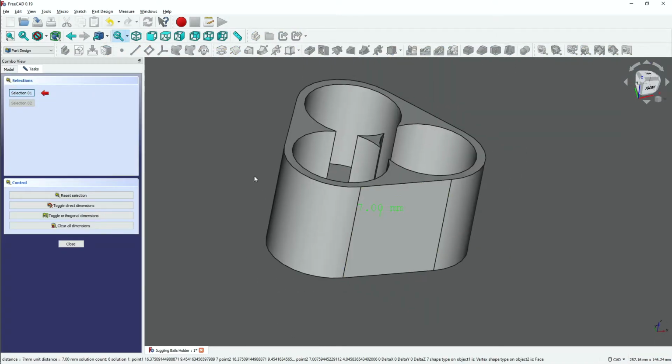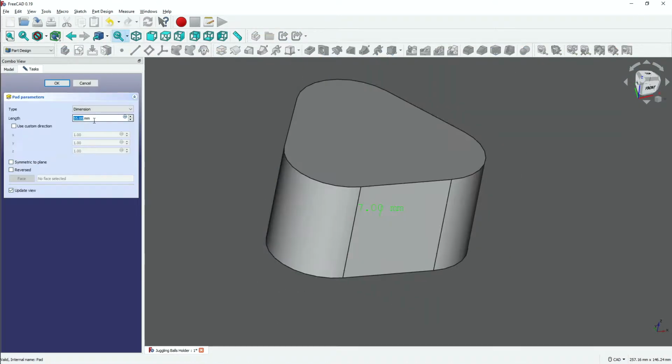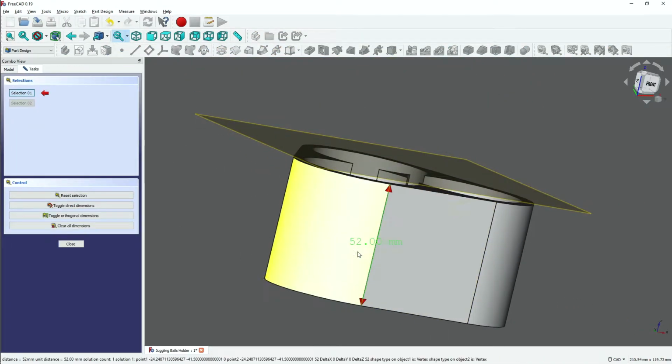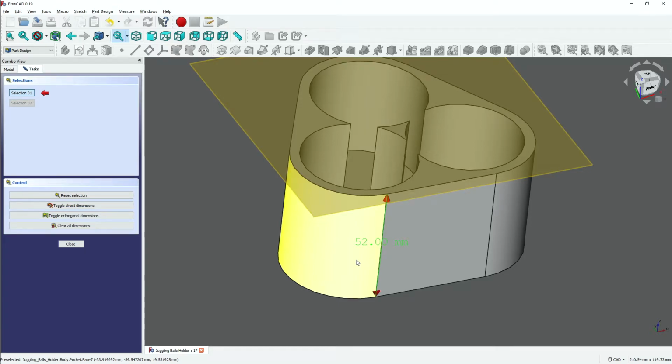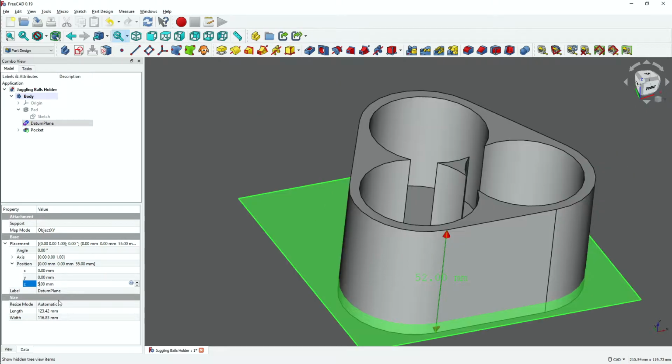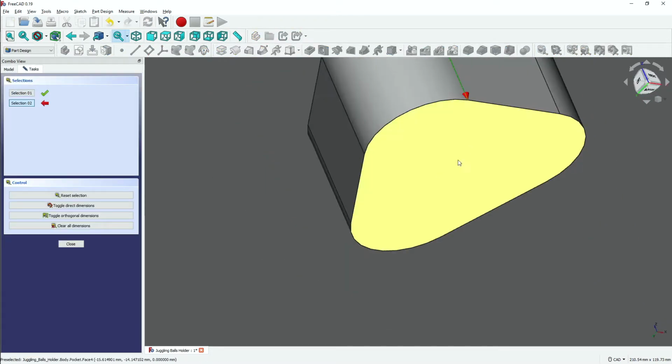And all those circles, every time, they always share the same center point. And I did that by measuring that line they go from to the origin. And I made them all the same distance, which I believe was 28 millimeters. So here I'm creating another datum plane.